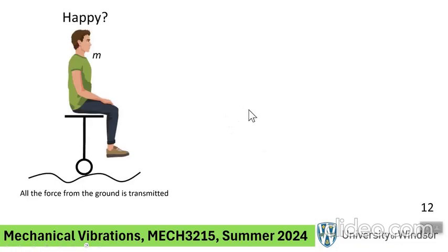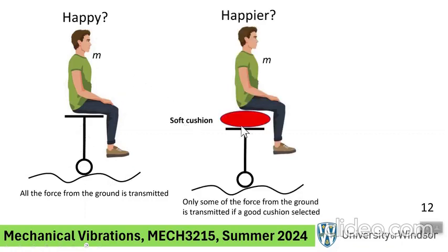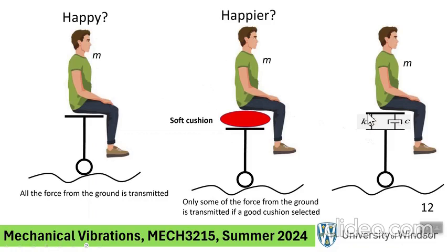All right, so what's the story here? Car transmission, bumpy road. Are you happy? Probably no. But you put a pillow underneath you. Are you happy? Well, why are you happy? For sure. So essentially what you have done, you have designed a mass, spring, damper system, which puts less force into your body.